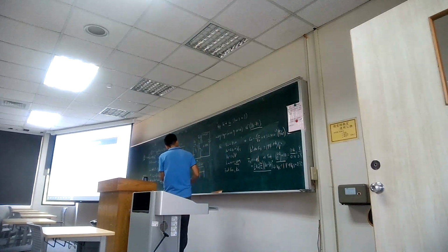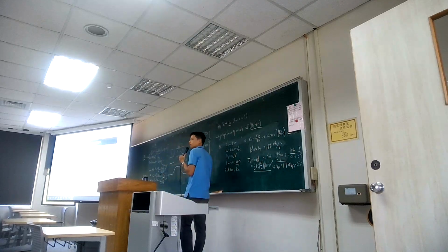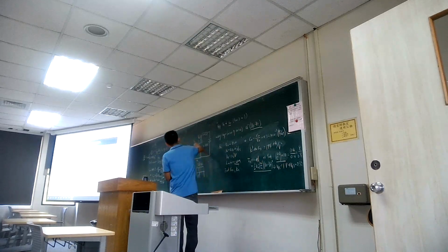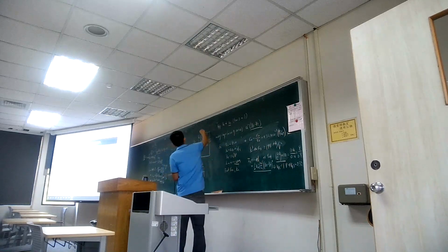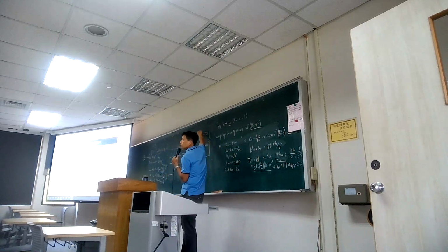Here's out. So if your input voltage is high, like a label of 1 and label of 0, it is typically 5 volt. Here's typically 0 volt. If you apply 0 volt, what does this mean? You turn off the channel, there's no current flow. Once there's no current flow, what is the output voltage? Maybe I draw here's the output.